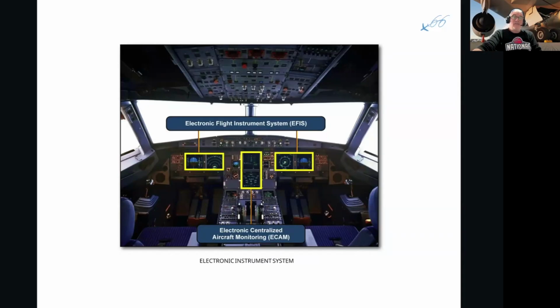Chapter 31, we talk about EFIS. EFIS, again, the A320 was one of the protagonists of the fully glass cockpit. So we used to have ADIs and HSIs, horizontal situation indicators and attitude director indicators, that were two analog dials in front of each pilot. Now, with the invention of the so-called glass cockpit, the electronic flight instrumentation system, we can provide pilots with screens where they have multifunction displays. And that's what we did.